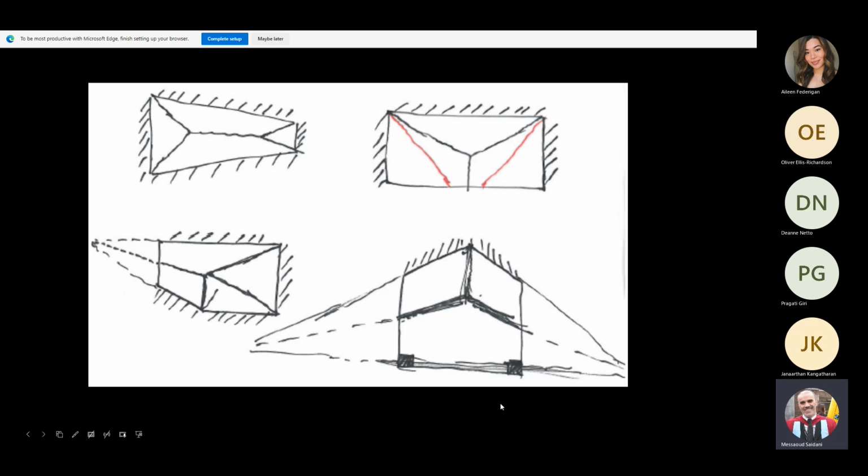Finally, we talked earlier about the columns, and we said that the yield lines go over the columns. The yield lines will pass over the columns. So what you have here is a slab, which is simply supported on these two supports, and is free on this support here. But it is supported on these two columns at the corners. So in that case, the yield line will start at the maximum curvature there. It goes to the point of intersection of the supports, which we have here.